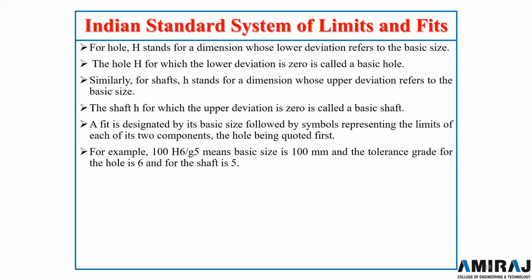A fit is designated by its basic size followed by symbols representing the limits of each of its two components, the hole being quoted first.